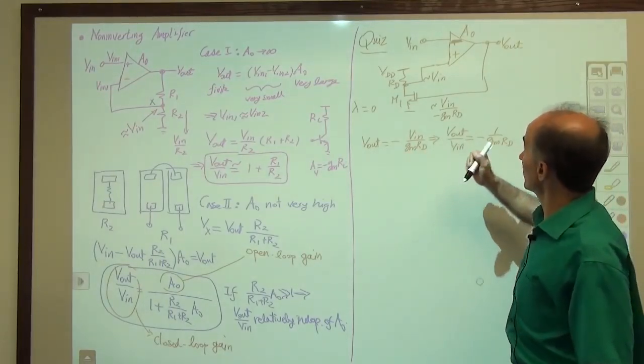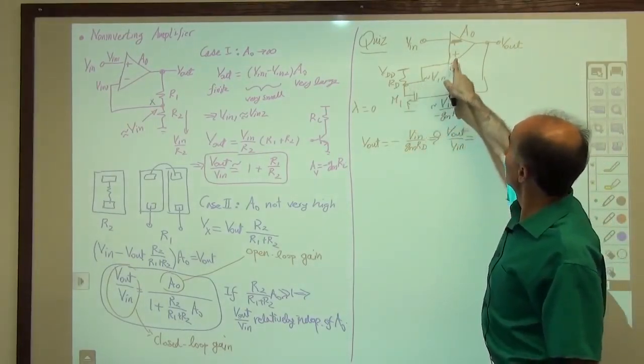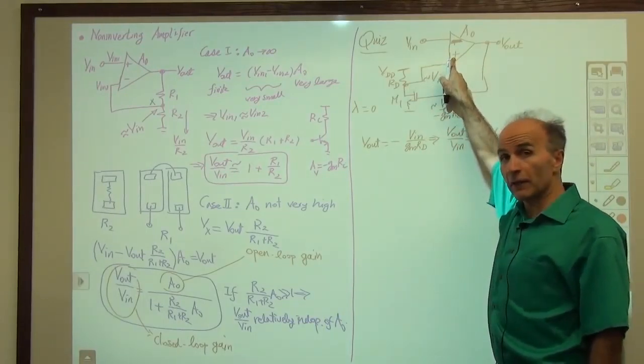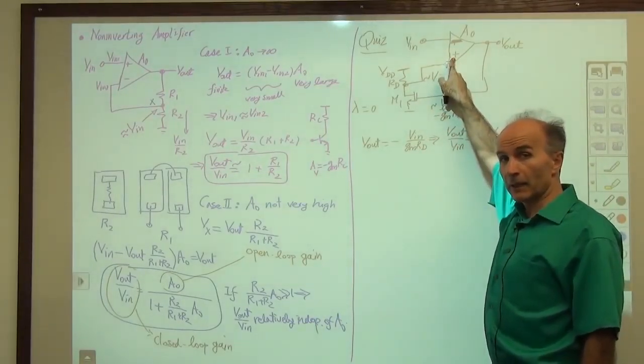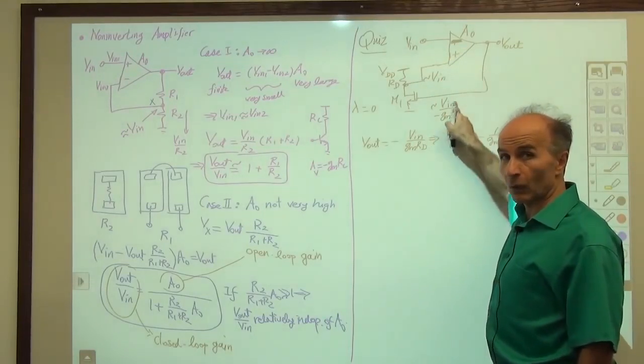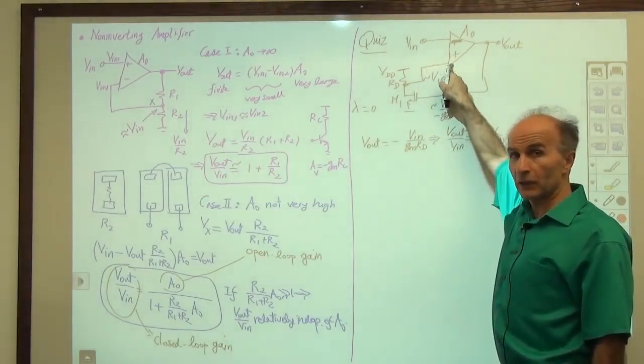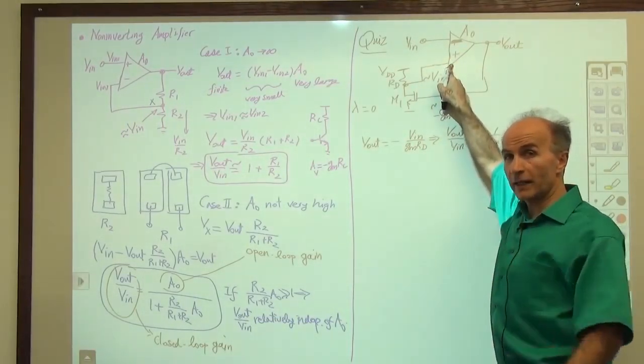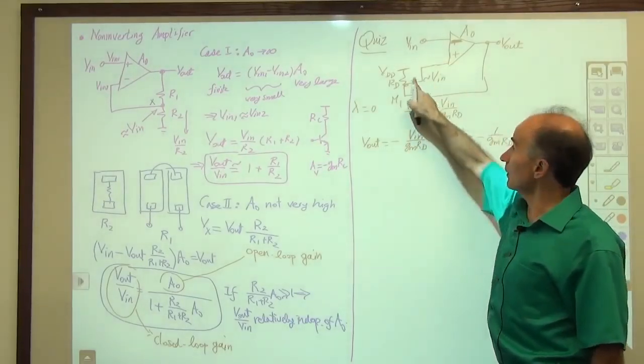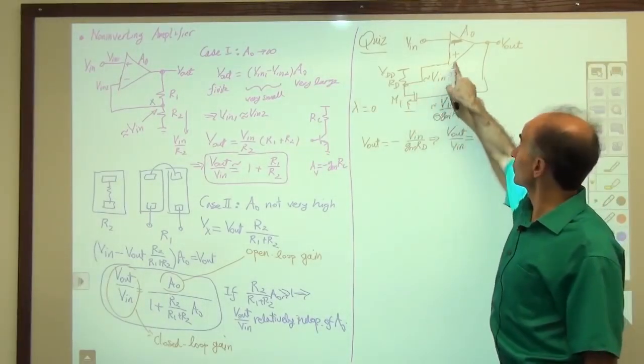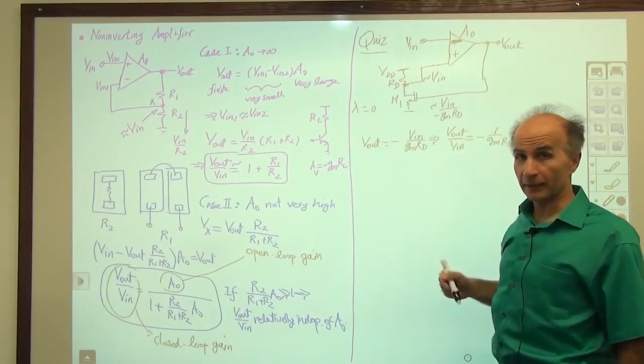All right, as you might have noticed, I have connected this to the non-inverting input of the op-amp because I want this whole loop from here to here to contain one inversion. The inversion is already provided by this, so this should go to positive, not negative.